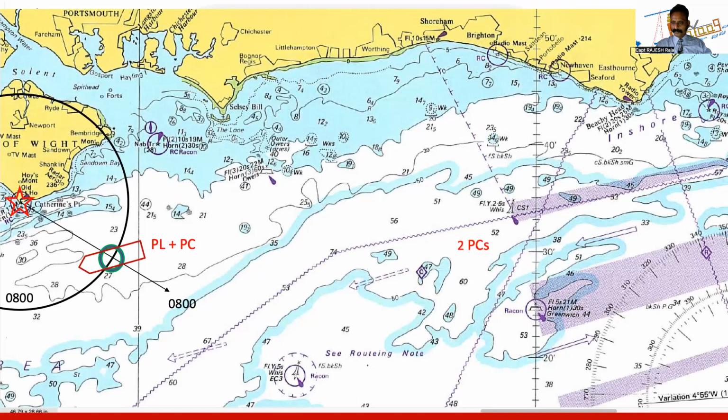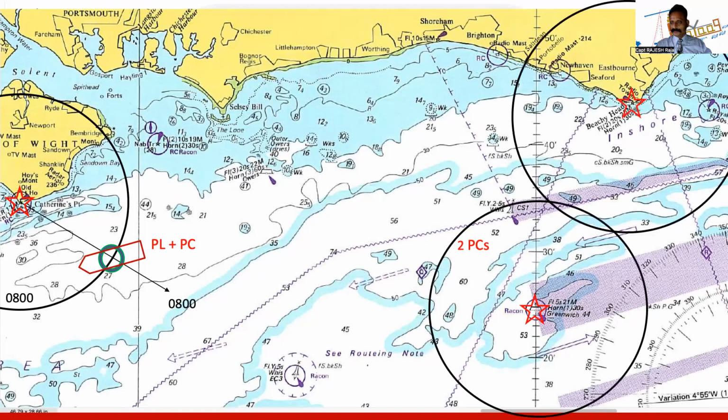Let us look at two position circles. This is Greenwich Buoy, and I'm looking at Beachy Head Lighthouse. So position circle, position circle. You can see I got ambiguity. And you can see I marked one with red. Why? Because obviously there is a traffic separation scheme implemented here. So you cannot be in this purple or violet color area. So you can be only on this. So you might be most probably traveling westerly.